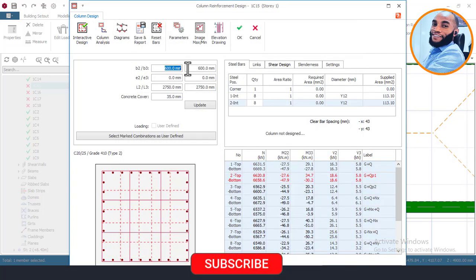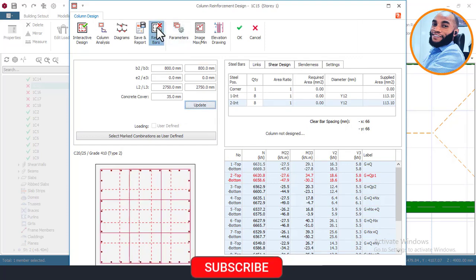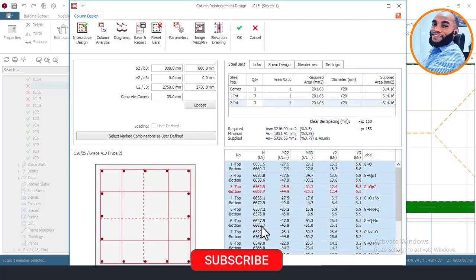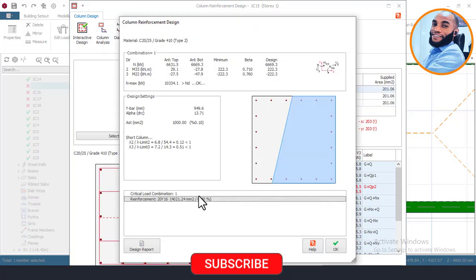Now most people can go and increase their column size to be 800 by 800. Then we set bars and click on this. It's still okay if you want that. I see that the more bars we add, the more we increase the size of the column, the smaller the bar size it uses. But I can see that it's giving me 16 number of Y20. So you can see that the more you increase your column section, the smaller the bar diameter you use. If I increase to 1 meter by 1 meter right now, you can see that we will be having Y16 on this bar. Update now and do this right now, so that we have Y16.